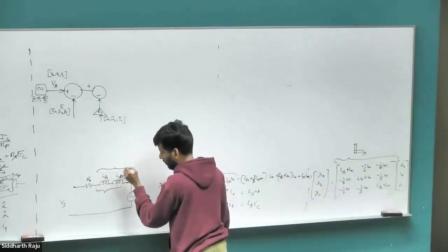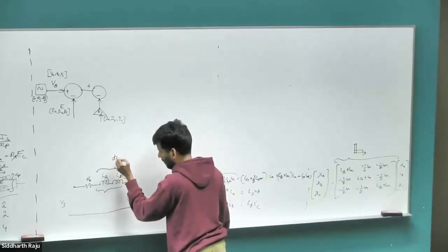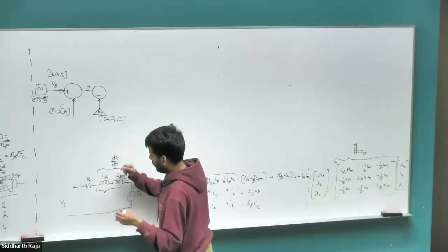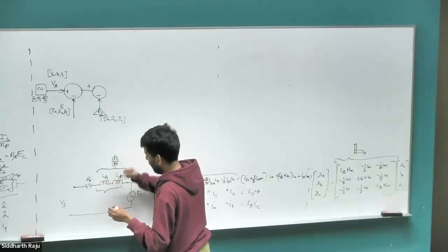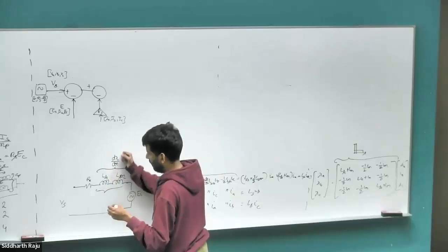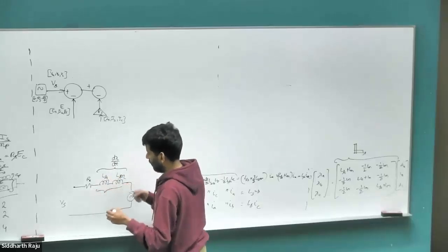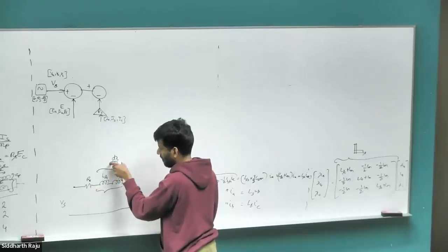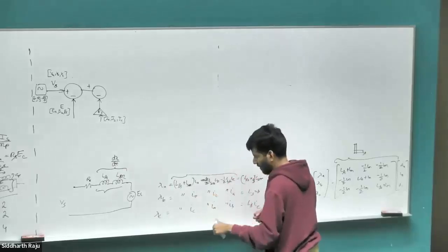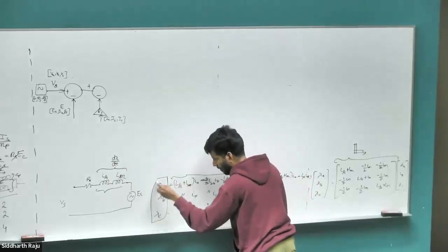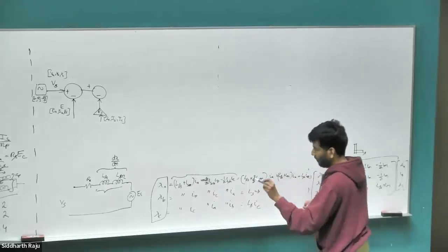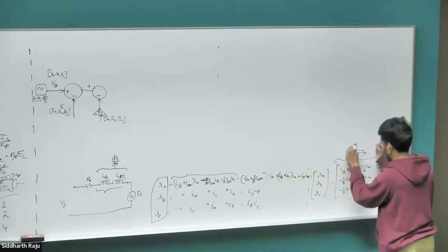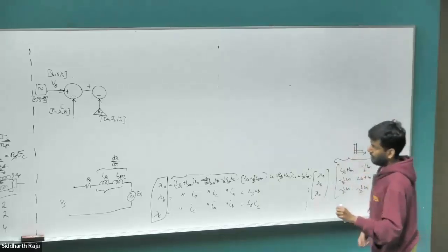Now what will be this voltage? This will be d lambda divided by dt. The rate at which the flux linking this coil due to its own current is varying is what is producing the EMF across this coil. So if I subtract all of these terms, what I'm left with is the voltage across this coil, which is the same as d lambda by dt. And what are those lambdas? Those are the lambdas of each of those coil windings without any influence from the rotor magnet. So I have this flux linkage, I divide it by the inductance matrix, I would end up getting the current.